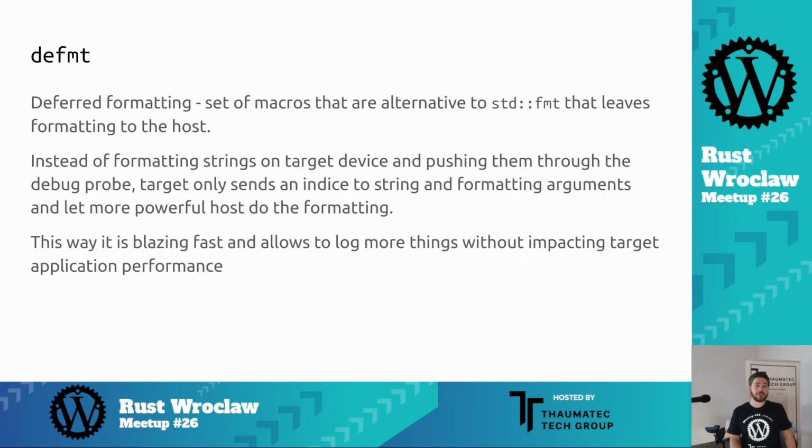So you have different alternatives, but the problem is that if you want to format strings on the CPU and you just use it for, let's say, miscellaneous logging, not for the real application part, just for you as a developer, it is quite heavyweight, because it is slow and it can impact the operation of your MCU, since this is a very constrained device, with low processing power. Just parsing the strings and sending them out to your debug probe might be time consuming.